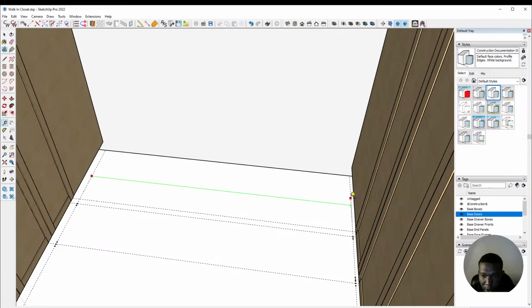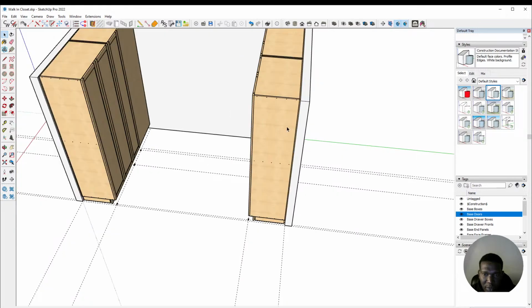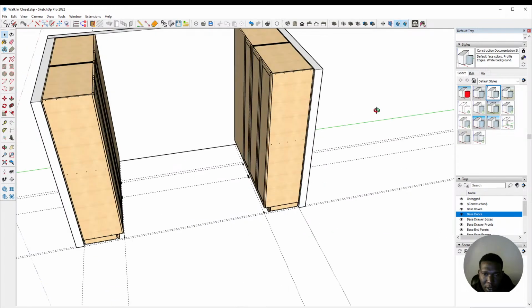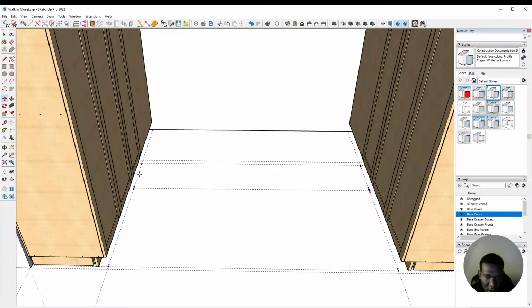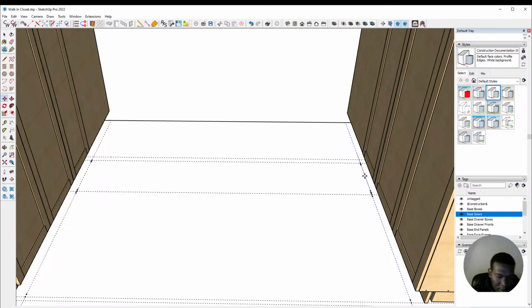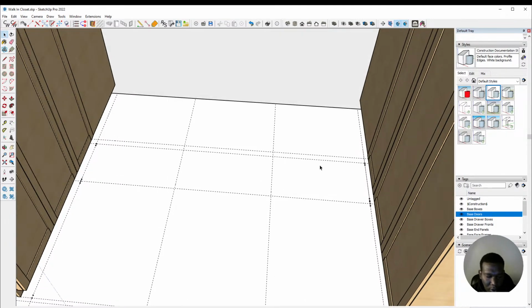So from there to there we have 90 inches. So let's just say we want to go that. Let's make all of these 3 boxes here the same size, so the cabinet maker can just make 3 boxes and then make the insides different. So move this one here, Control to copy, and then place it there, divide it by 3, then you have 3 equal sections. Select one of those lines and delete.